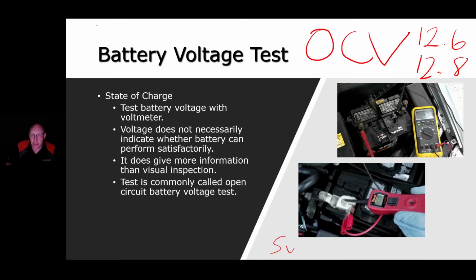Surface charge means that there is a charge on the surface of the battery and the surface of the cells of the battery that needs to be removed. That is not usable charge. It's really unusable, but it's measuring and throwing your measurements off. So it's an unusable charge, but it's making it look like it's more than it is, right? So you need to get rid of that.